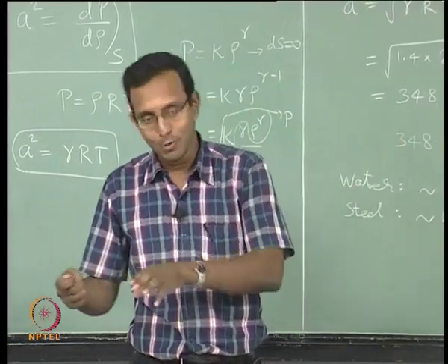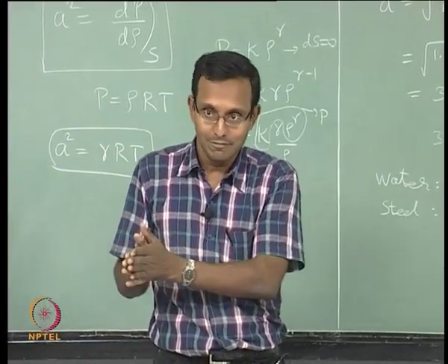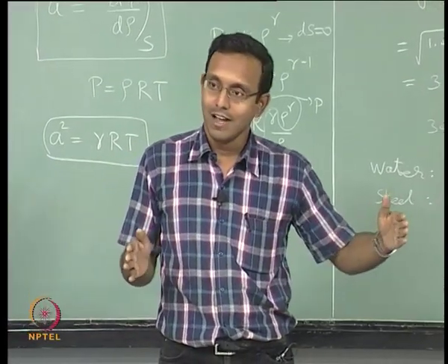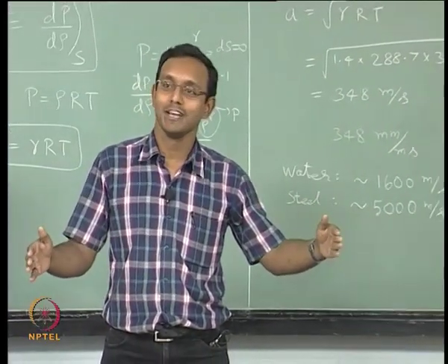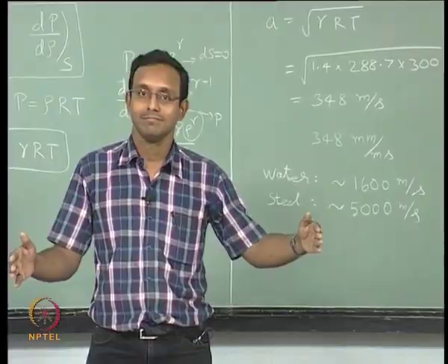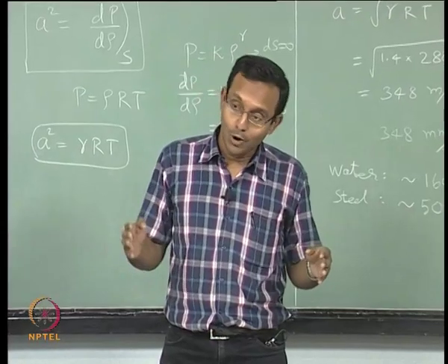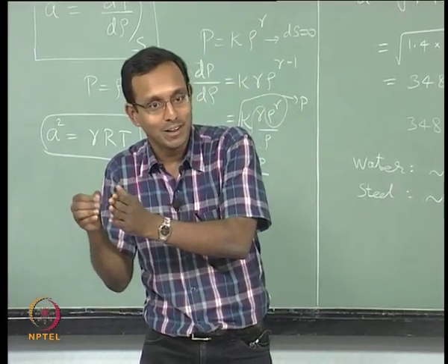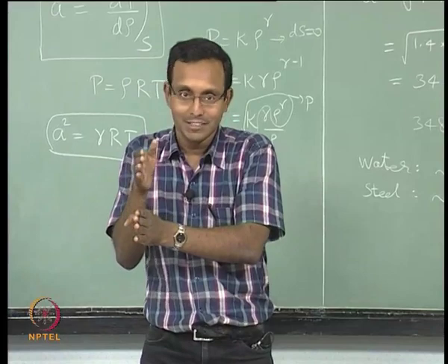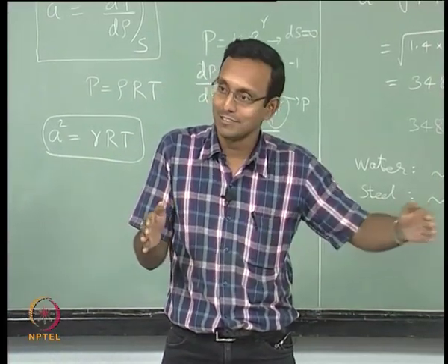Now I am going to take a hammer and hit this steel rod. The wave is going to travel at the speed of roughly 5000 meters per second. If I have 5 meters, it is going in 1 millisecond. That is of the order it is going to take. Now how did it go through this whole process? Those molecules in the top layer are colliding with the next molecules, they are colliding with the next molecules, and it just keeps on going like this.